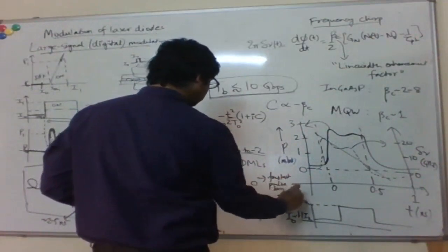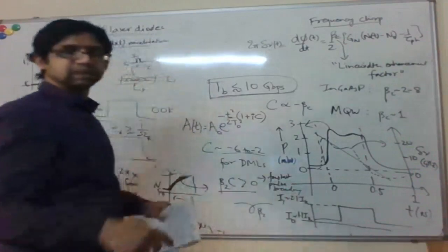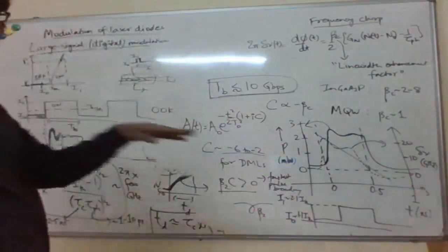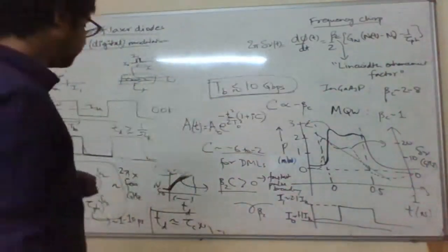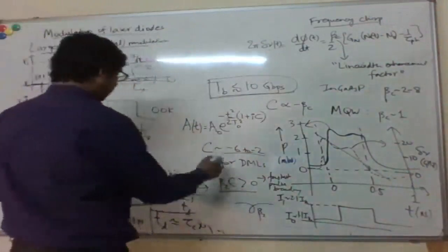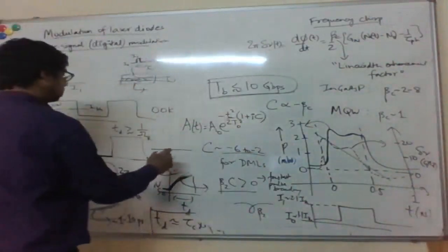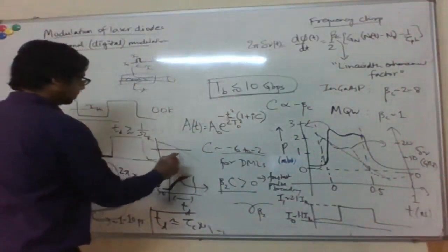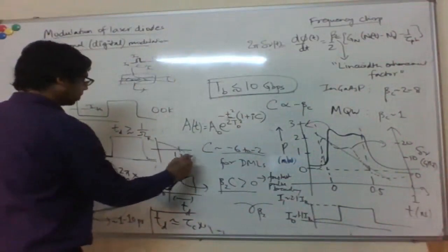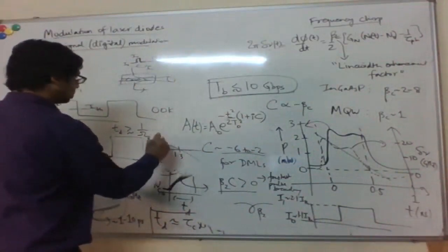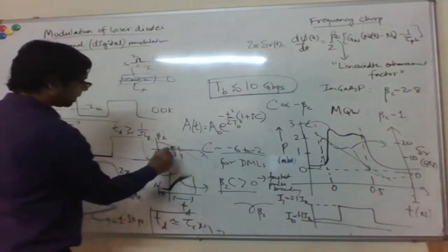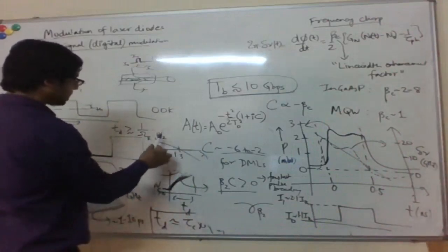So what you want is beta 2 and C to be of opposite signs, so that actually the pulse first compresses for a certain time. So again, recall beta 2 looks something like this. It crosses 0 at 1.3 micron, and then becomes negative. So D is opposite sign of beta 2.